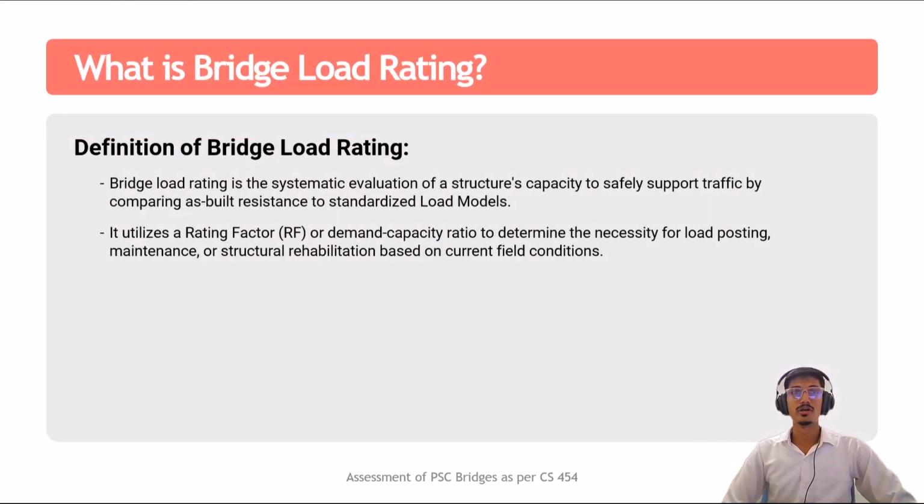So to start with, what exactly is bridge load rating? So in simple terms, bridge load rating would tell us how much traffic an existing bridge could safely carry today. So we'll be taking the actual site conditions as per today. So it is not necessary to do it only for the old bridges, also for the new bridges it could be done. And we compare the current capacity of the bridge with the standard assessment load models and express this as a factor. So that factor is called the rating factor.